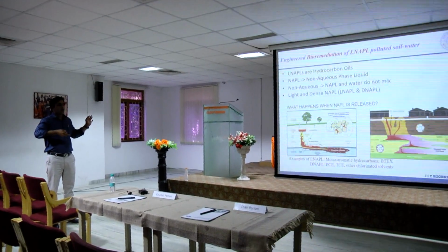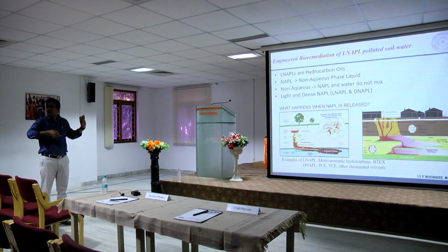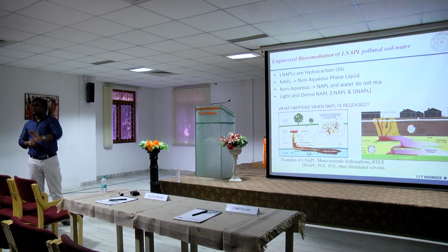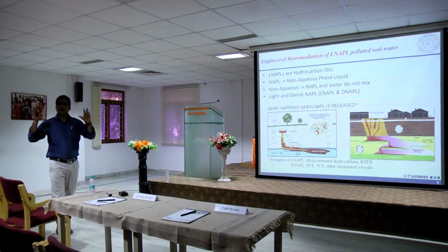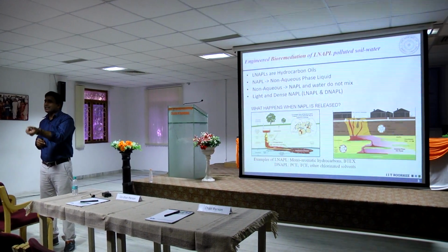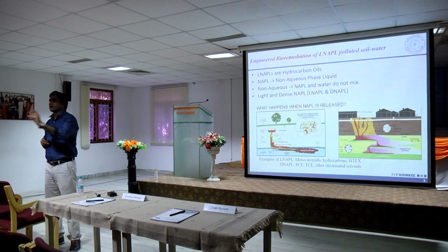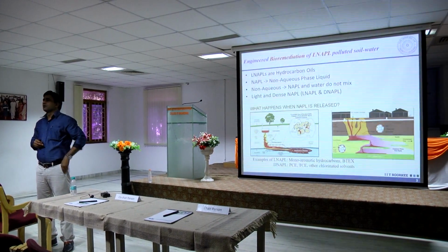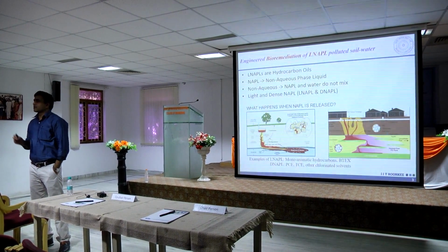Now a portion of these, in this direction, a small layer of these LNAPLs is made over the water table. So maybe 5 liters of LNAPL leakage can cover a large area over the water table, and a very thin layer of the LNAPLs can be made in the capillary range that is nearby to the groundwater table. I'll give one example.